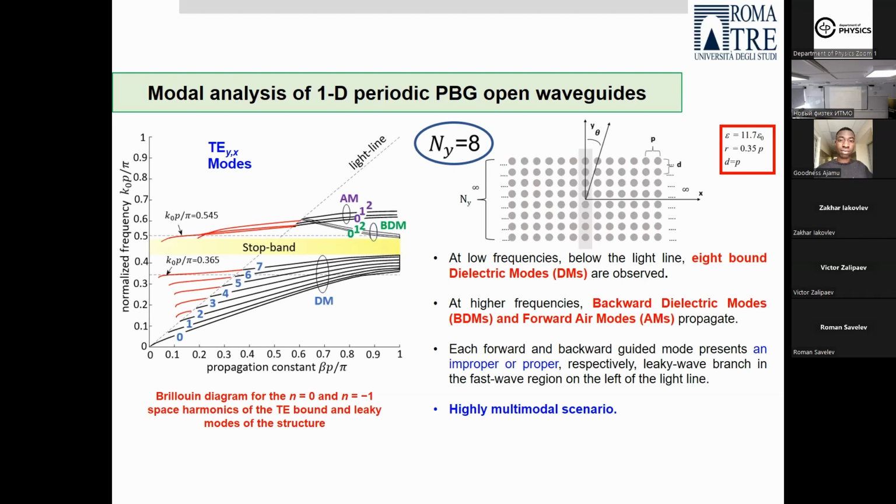Of course, we have the complex continuation of these modes in the radiative region, which are marked by red. But for the antenna design, it would be meaningless to take the frequency region here. Why? Because at a fixed frequency, of course, guided modes will also be excited. And when the guided modes are excited, it degrades the efficiency of the radiation system, for example, an antenna.